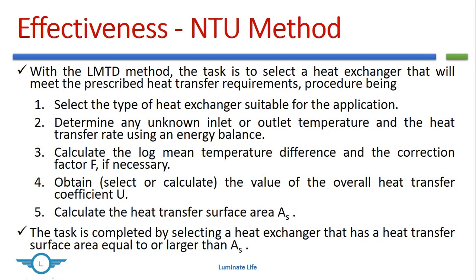Now with the temperatures, we will calculate the log mean temperature difference, LMTD, and the correction factor if it was a cross flow or a shell and tube heat exchanger. Then we will either calculate the overall heat transfer coefficient U, or we will select it corresponding to a particular value from the data book.